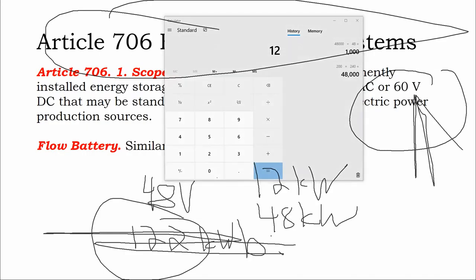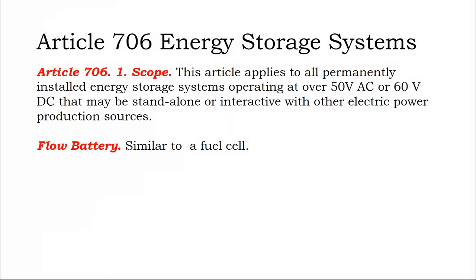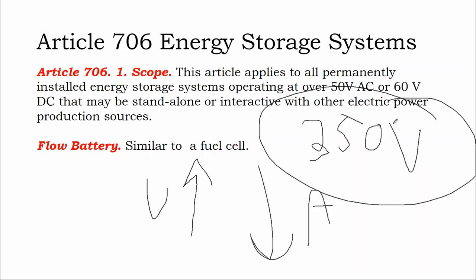So what is safer and more cost effective is to increase voltage and decrease amperage. With the Tesla battery and with other battery inverters that were made specifically for lithium ion, like you see in electric vehicles for that matter, you see a move towards a 350 volt platform.